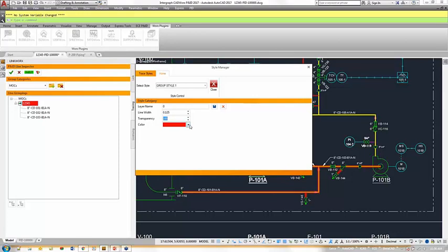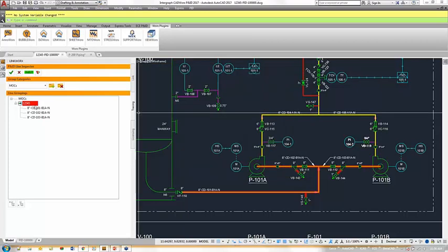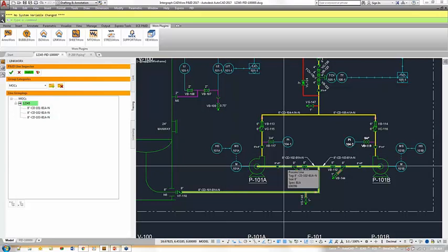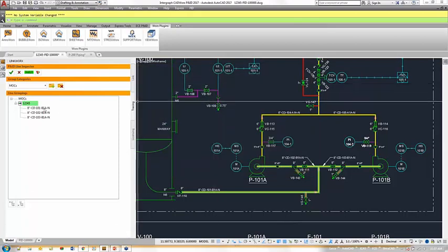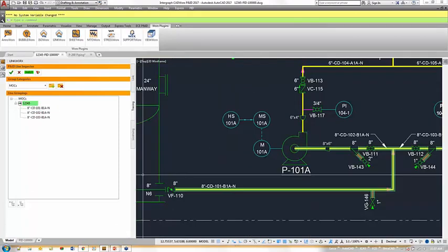But out of the box, we're going to apply style 1 to group 1, style 2 to group 2 automatically. So there's really not much setup of any to do unless you opt to go change the color. Once I change the color of group 1 here and refresh it, we're going to get back to green, so just changing from red to green, for example. Or if I want to change the width to 0.25 to get a thicker line, then now I'm back to a 1/4 inch instead of 1/8 of an inch of tracing width.